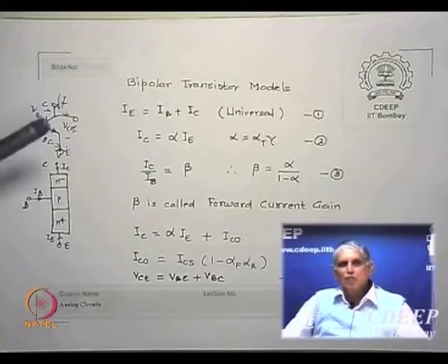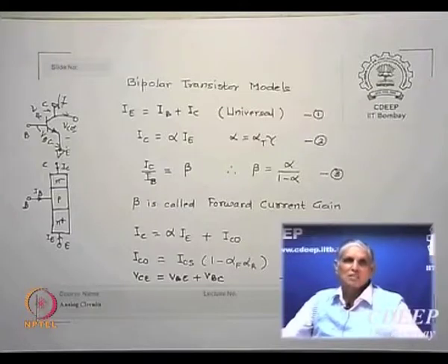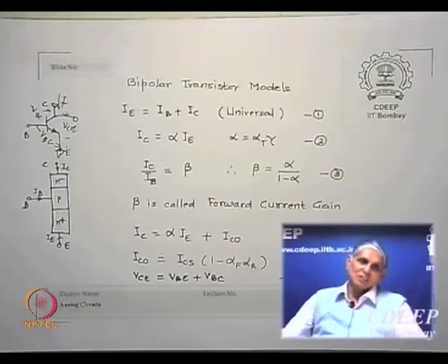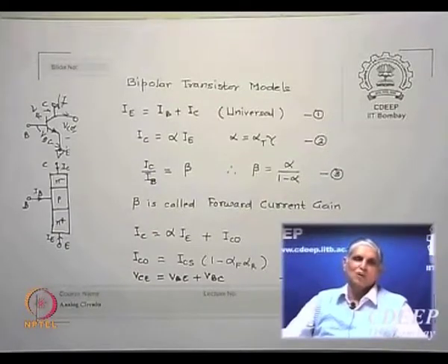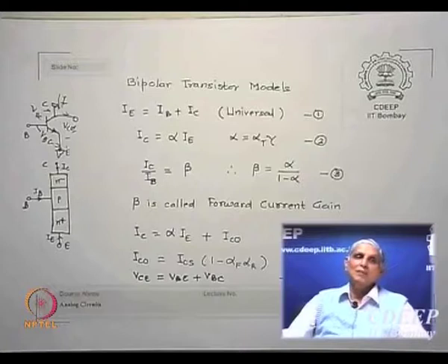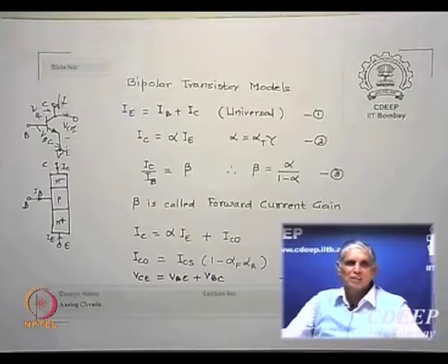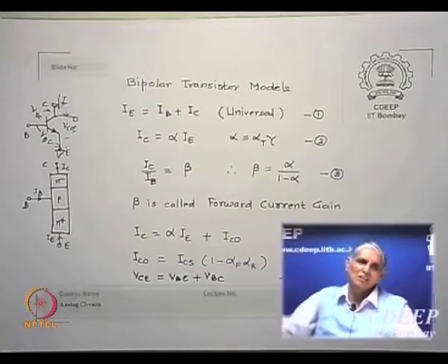If the transistor is in cutoff mode, when both junctions are reverse biased, then neither junction is conducting and only reverse currents flow, so you may say the transistor is in the off state. Contrary to that, if the base emitter junction is forward biased and the base collector junction is also getting forward biased, then both collector and emitter will emit carriers into the base. There will be a huge base current. Conversely, if there is a huge base current, the transistor will enter saturation. Is that clear? That's the theory which we learned earlier, hopefully.